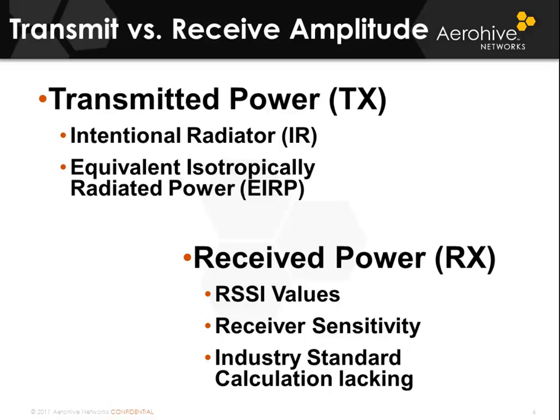There is really not a standard for calculating this, so two devices that are exactly the same distance from a transmitter could be receiving the same signal but indicating different values, just because they're using different chipsets from different manufacturers or from the same manufacturer running different versions of firmware developed at different times.